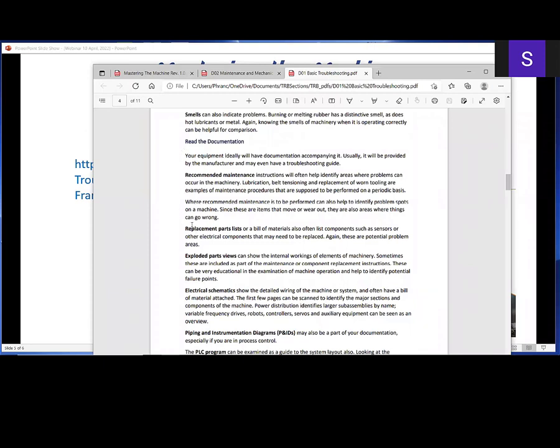You can also identify things like, do we have a replacement part list? Does it list every part in the machine? And can I identify, for instance, alternative parts? Photo eyes to me are photo eyes, especially simple photo eyes. If they're just on and off, they're through beam photo eyes or retroreflective. It doesn't matter if you get them from Banner or Automation Direct or Keyence or whatever.